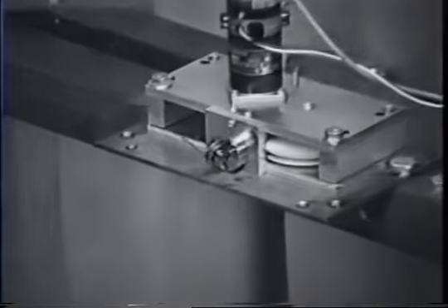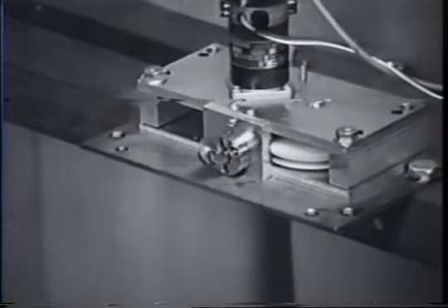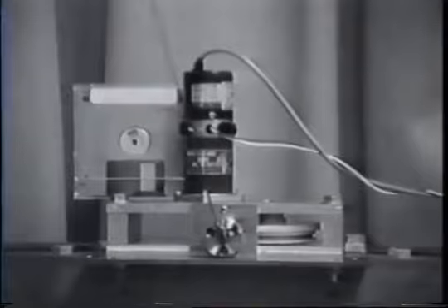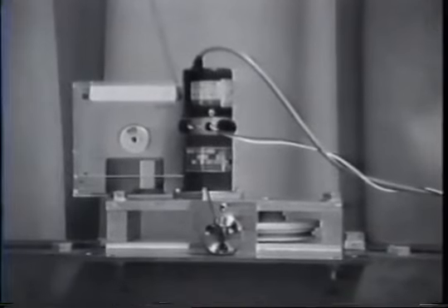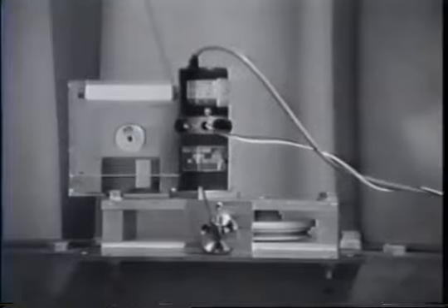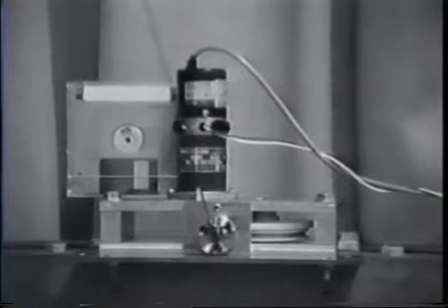Falcon means fast load conveyance, and Falcon 7 has 7 wires to realize 6 DOF motions. Each wire is rolled by a pulley which is connected to a DC servo motor. The dimensions of the frame are 1.4 x 1.4 x 1.2 meters. The wires are made of steel, 0.5 millimeter in diameter.